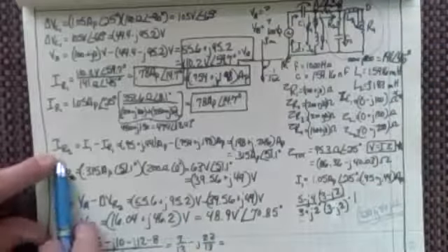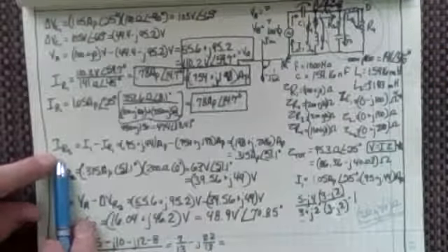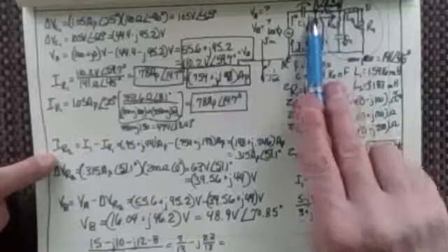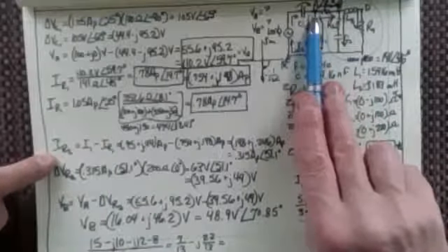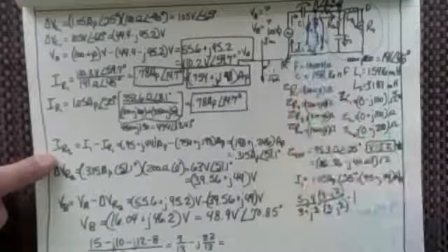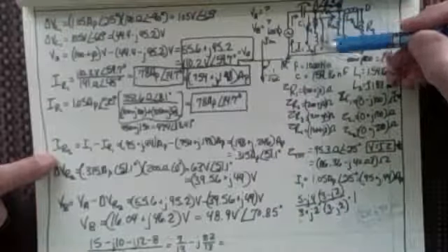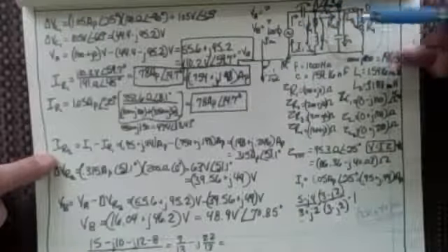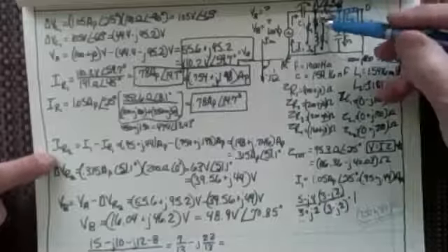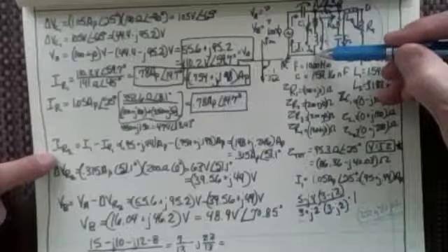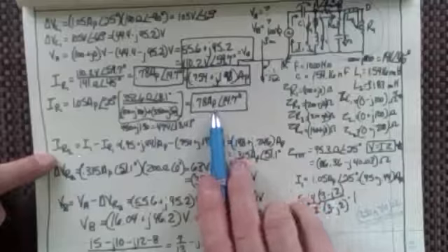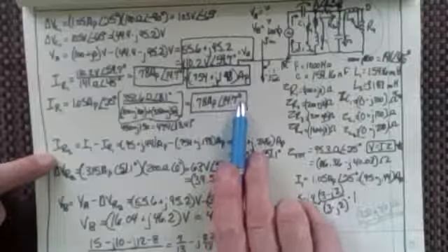So I said, well, okay, I sub R2, the current that's flowing through here, because if this current's flowing into the node at A, then the current can only be flowing out down here, and it can be flowing out over here, right? And we know what the current is flowing down through here. That's 0.78 amps peak at 14.7 degrees.